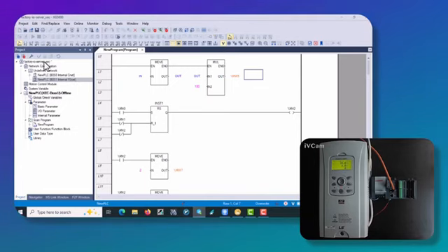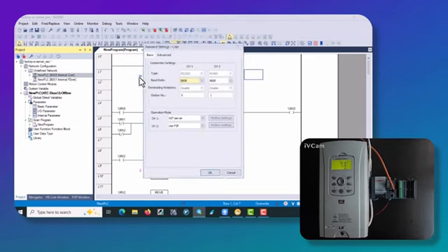Now, I want to use the LSPLC to connect to the inverter via Modbus RTU over the RS485 network. How do I connect to the inverter via RS485? What should I do? When you click on this sync section, the activation window will open for me. Channel 1 is my RS232 network and channel 2 is my RS485. I want to connect to the inverter via the RS485 network, so I'll do my settings on channel 2. I set the network to RS485, the baud rate to 9600 and the station number to 1. Then I go to channel 2 and set channel 2 to the Use P2P option. I select it and press OK.